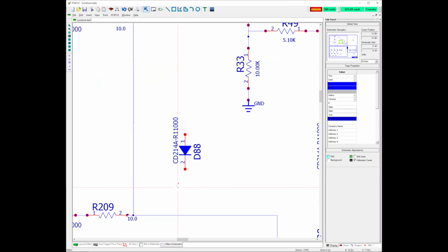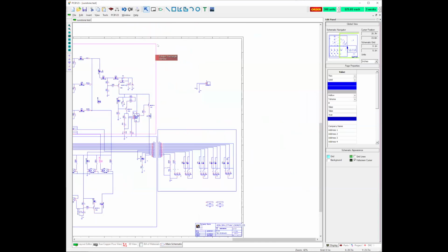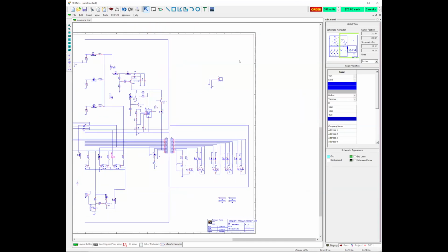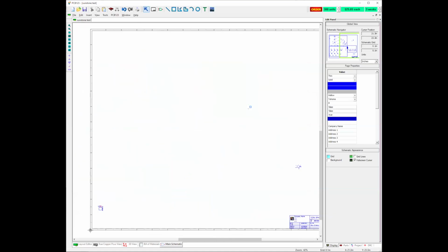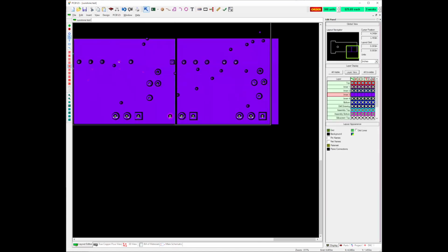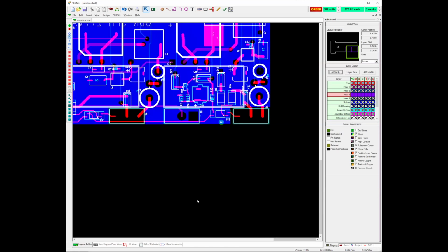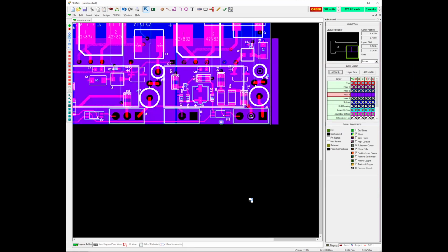And we looked and looked and could not figure it out, because it was such an innocuous little thing. It's pretty simple. Finally, we discovered that these polygons that you can add create boundaries, and they basically lock up your design. My board still works just fine. It still does all the things it's supposed to do, but in the schematic, these boxes. So just don't use these boxes. That was a huge thing.